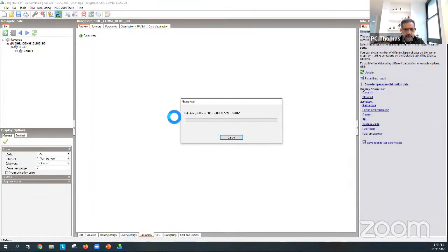All right, so any questions on how we set up the simple air conditioning model? We'll do a detailed one next seminar that we have, but that's the simple air conditioning model. For most things, I would suggest just use the package terminal heat pump, the PTHP that I showed you. That's fine.